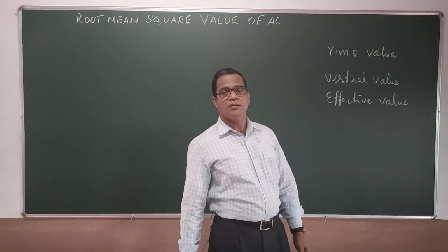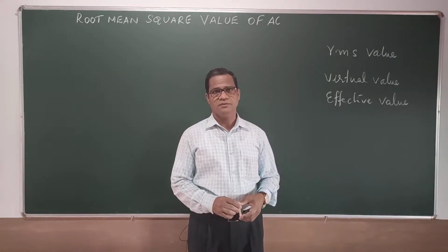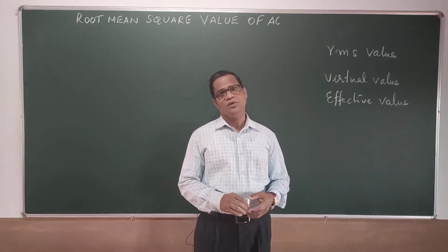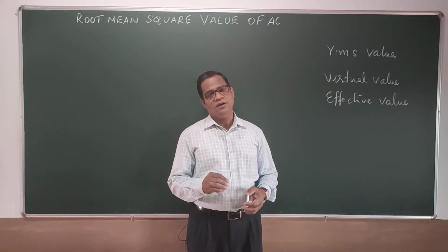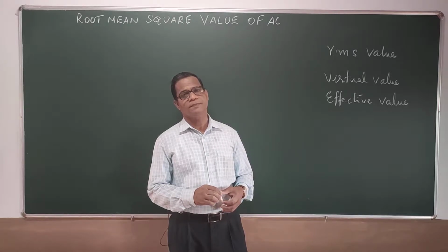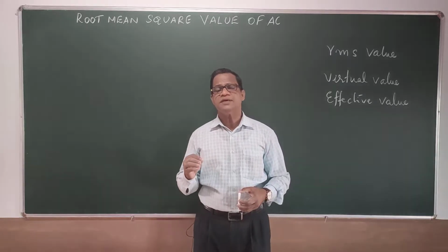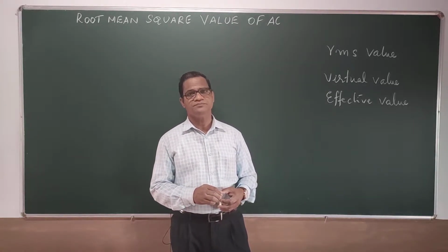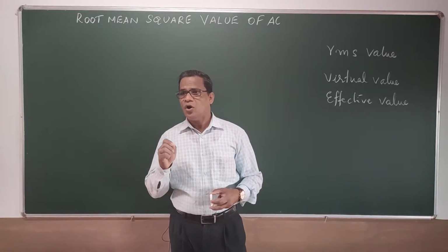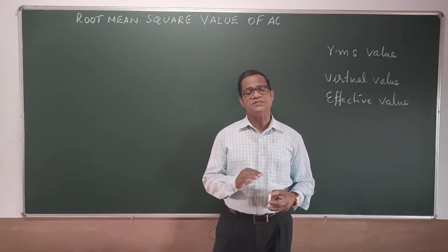Now, what is RMS value? It is defined as that value of steady current which, when allowed to flow through a resistance for a given time, produces the same amount of heat energy as is done by the alternating current through the same resistance for the same time.